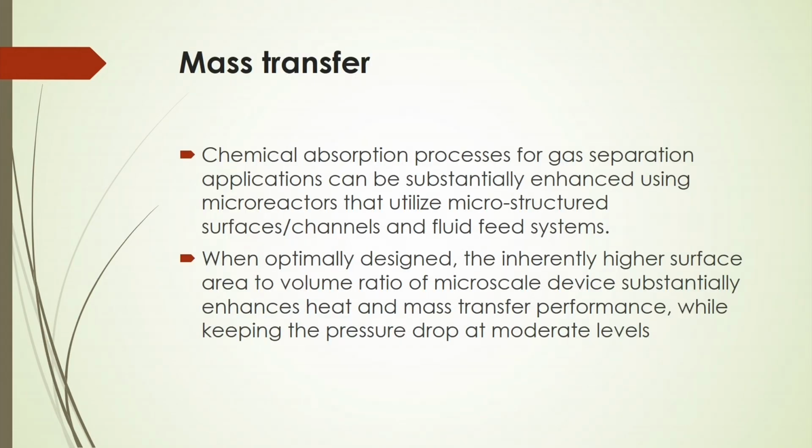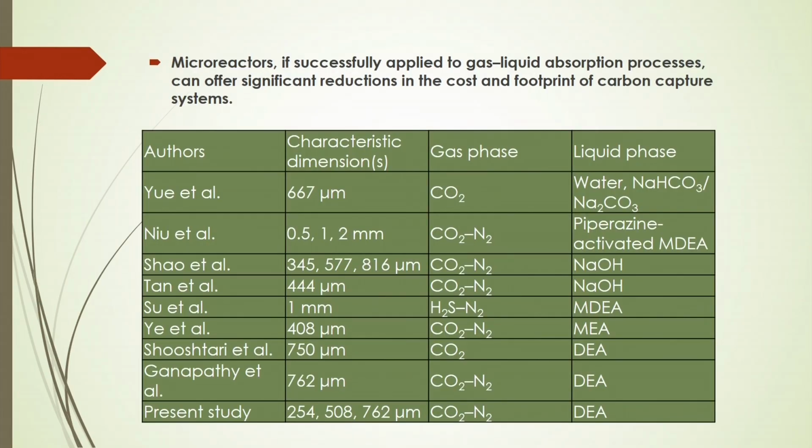And then mass transfer. Of course, based on this mixing characteristic, you can analyze mass transfer. Higher mixing will give more diffusion and more effective mass transfer, because in this case there is no back mixing, which may sometimes hinder mass transfer efficiency. In a microchannel based reactor there will be no back mixing, so in that case you can increase the mass transfer by this channel.